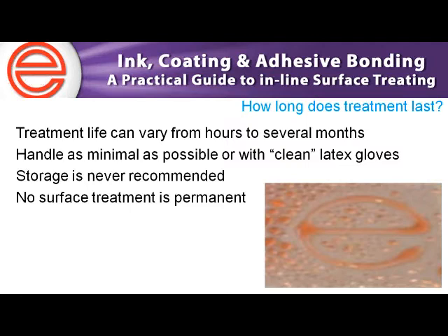Some of the culprits, the materials that tend to drop their surface energy very quickly, are anything that's a very pliable plastic, maybe something with plasticizer in it, or very bendable. Those tend to be the most difficult to treat for longevity. The harder plastics tend to hold surface energy the longest, but regardless, we do recommend that you do a longevity test to confirm what that window of opportunity is.